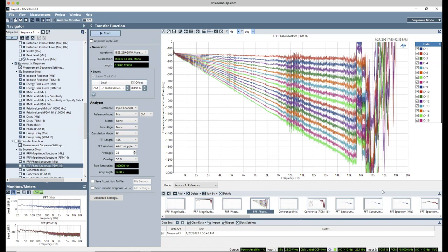But this is a quite handy way of doing things, particularly, for example, let's say we're testing a smart speaker where we can't use a sinusoidal signal for the test because there are voice processing algorithms that will ignore sine waves. We can use an actual speech signal as the test vector, still get our frequency response. We can still get sensitivity.